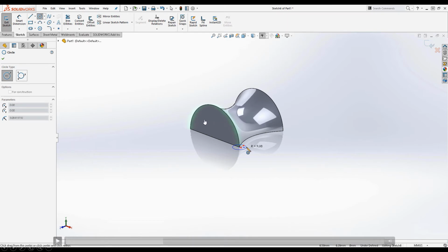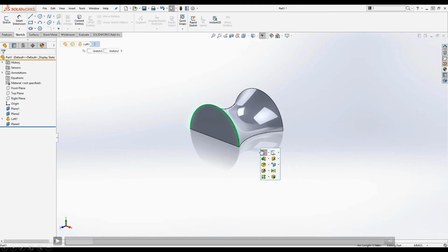The plane? No, so I had the shortcut toolbar that I used, and I just clicked sketch, and it made it pretty quickly. So what you're doing is you're just selecting an edge, and then you can go up here and select sketch, and it'll create it wherever that endpoint is. If I don't have a shortcut, it goes to the menu? Yep, yep. As long as you're hitting the sketch button.